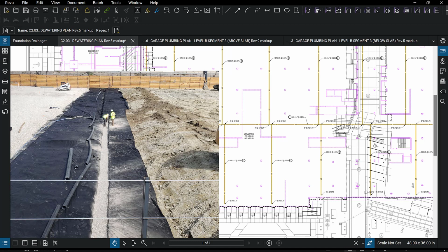They're going to put all the perforated pipe in the ground. They're just putting down the bedding layer now, setting the grade so that the slope is something that the pipe can drain towards this center one. Right over here is going to be the same thing. They're going to fill it up with a little bit of gravel to set the grade, and then they'll put the pipe in, set it to grade, connect it all. Got all the perforated pipe.